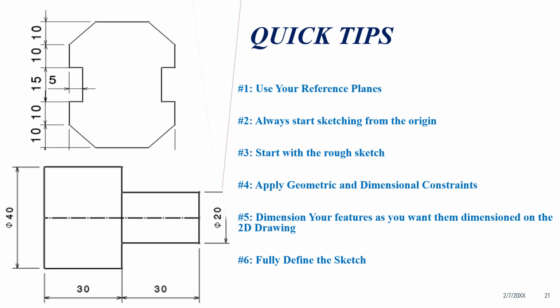Try to start your sketch with a rough sketch. Let's say you're having a clean model, as you could see here. Instead of dealing with each and every dimension manually, first draw a rough sketch and then start dealing with the geometric as well as the dimensional constraints.